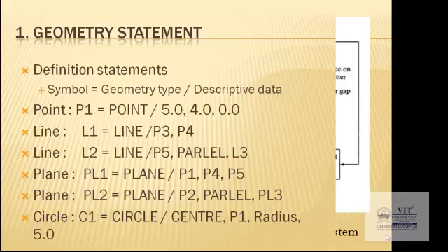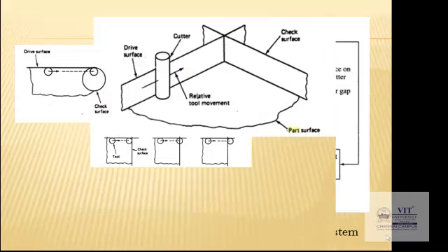Or you can communicate your geometry to the controller. So you have to specify this. Based on these parameters or commands that are given, it forms some geometry. So it forms the outer boundary of the particular geometry. For machining that outer boundary, the program is used. So this is how the motion takes place, how the tools are moving.